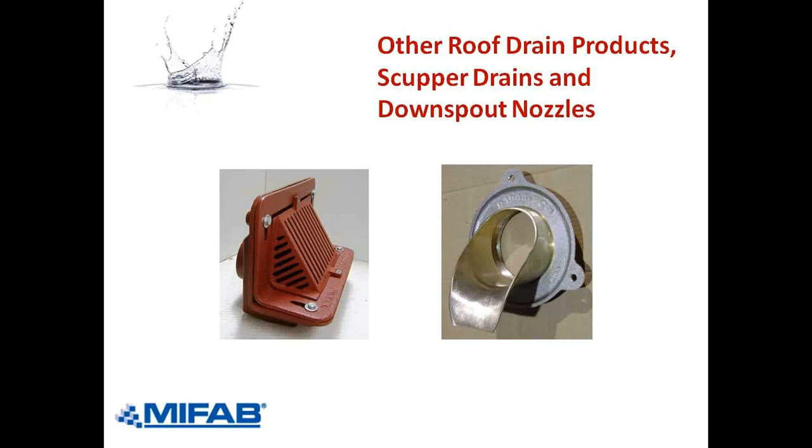The function of the R1200-R and W is to block water so that water goes into the primary drain that doesn't have that water dam or internal standpipe. We want the primary drain to take the rainwater first and then drain to the sewer. In the event that the primary drain gets blocked because of leaves or debris on the roof, plastic bags and so on, then most engineers will have a secondary overflow drain right beside it.